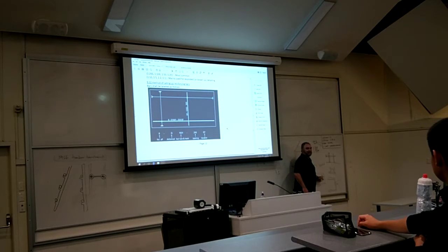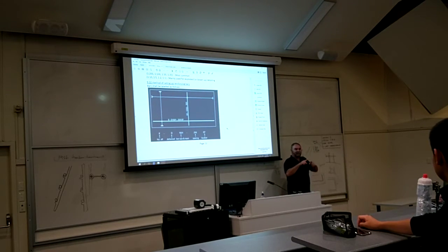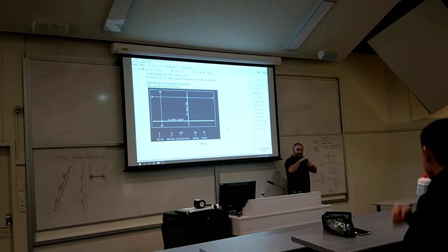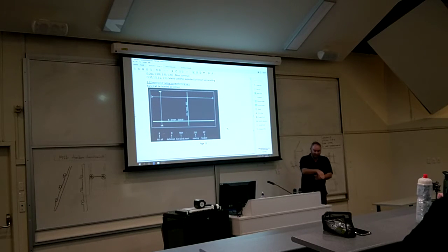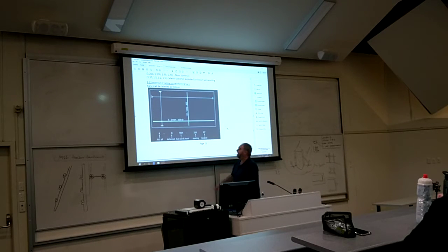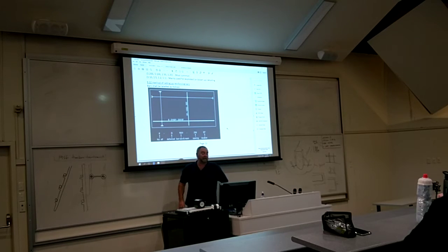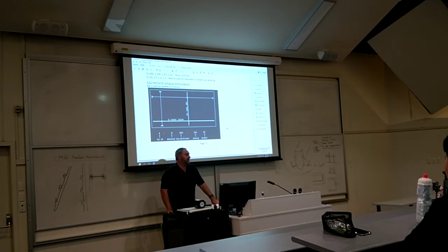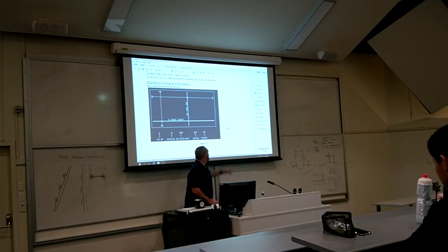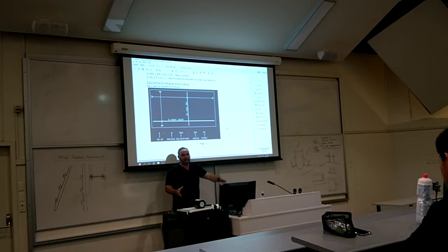In fact, most of them do. So therefore, you'll need to do a donut at the end to show that it bends down, because you're looking down on plan view. So that will have a donut here. Make sure the donut does not go past the edge of cover. Easiest way to do that, draw that as a P-line and offset it whatever the cover is. And then nothing will go outside it, right?